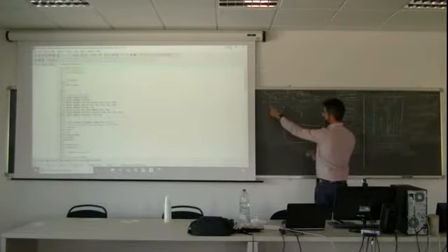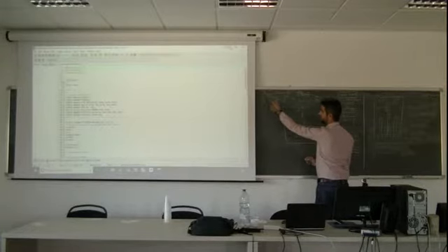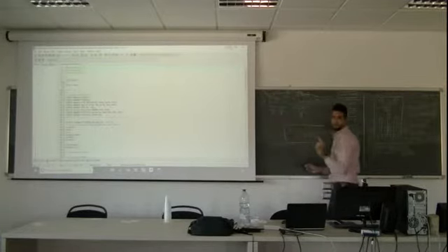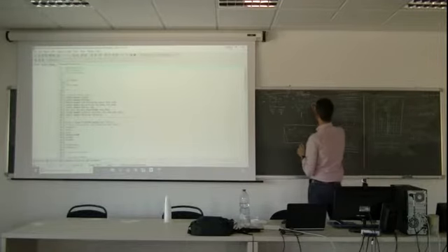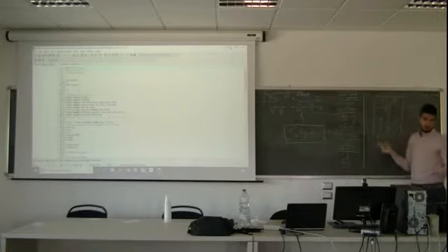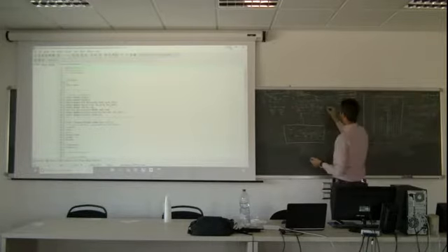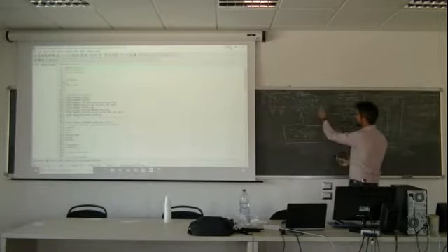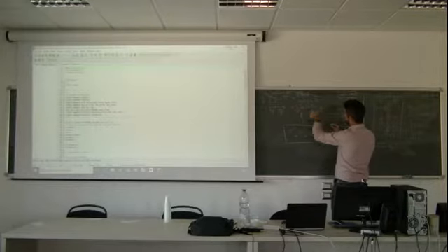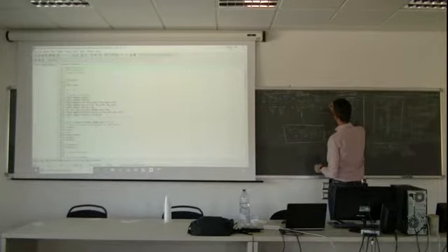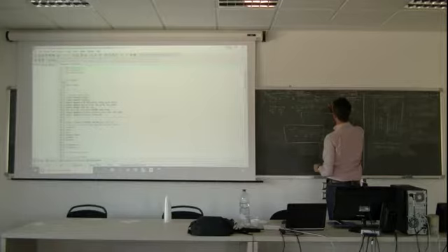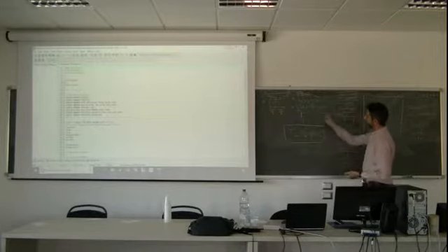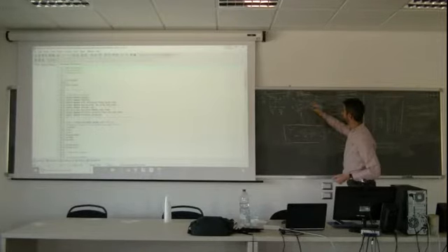The volume is this distance multiplied by the surface, because only this part is generating heat. So it is delta x1 divided by 2 multiplied by the surface multiplied by QV, which is the 500 watt per cubic meter. Minus Fourier here, minus k, that means plus k, TE minus TP divided by delta x2 multiplied by S, equal to 0. You see, because it's 1D, I don't care about S.